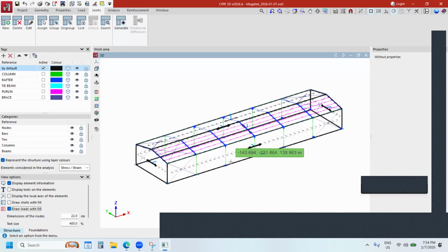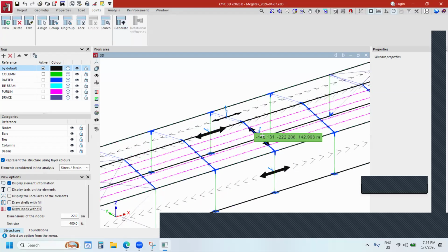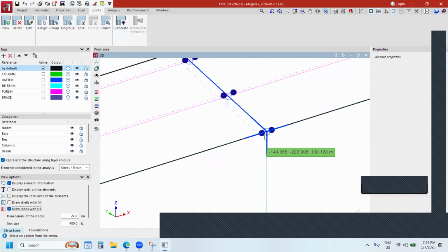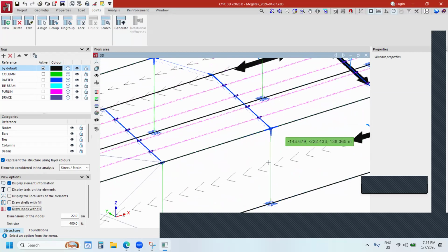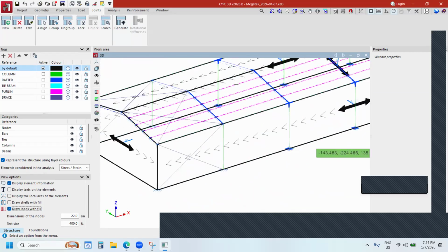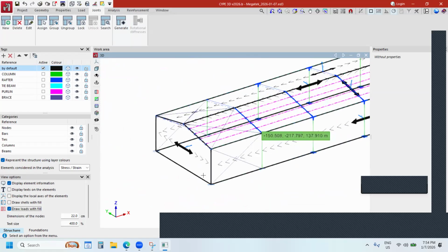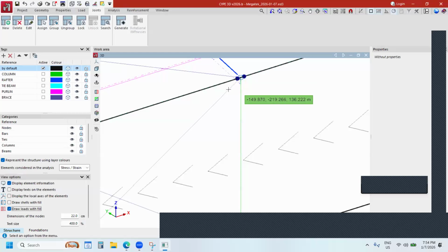And then if I accept, I would see what kind of connection I have. So here, the software is able to design the base plate, and design the apex. As you can see here, the apex is here. But here, the software is not able to design the connections because here we have the braces coming from the wall braces and roof bracing.